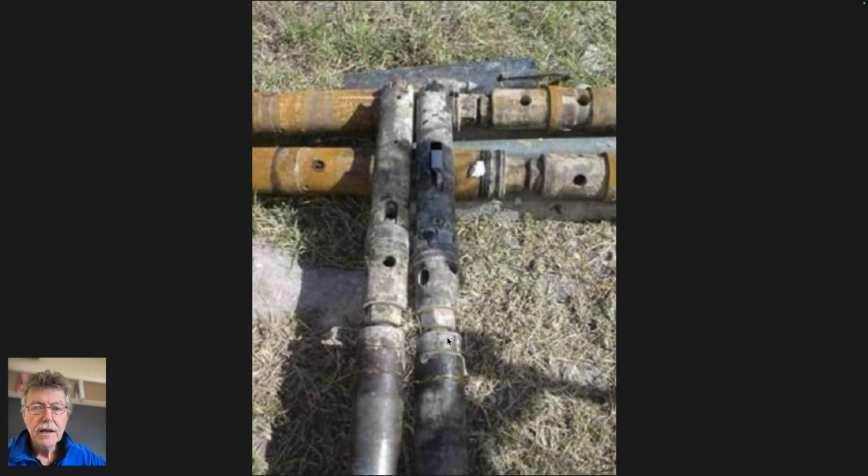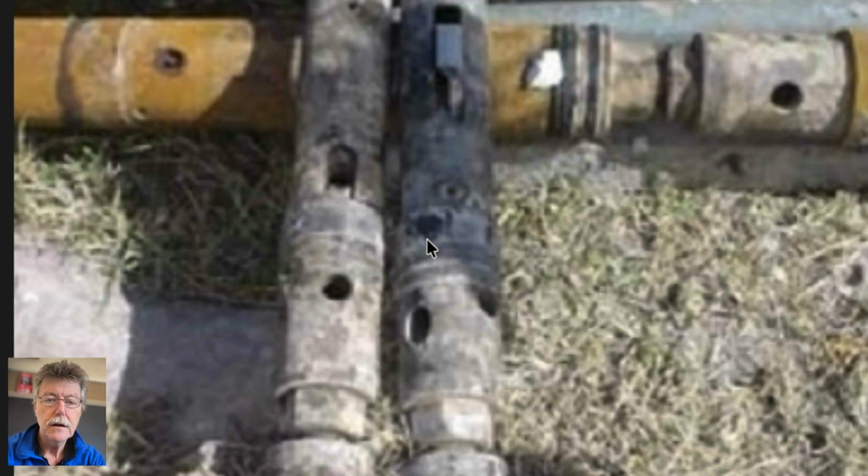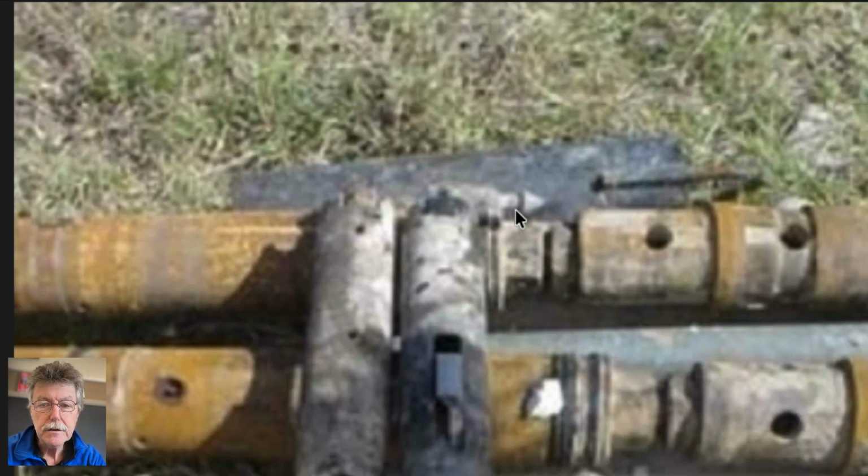And so that's it. And this is the top of the core barrel. So the top of the core barrel, if you see it here, has a little cone with a collar around it that's recessed. And this is exactly what the clip on the wire line is going to attach onto, and then it's going to pull out this whole assembly.